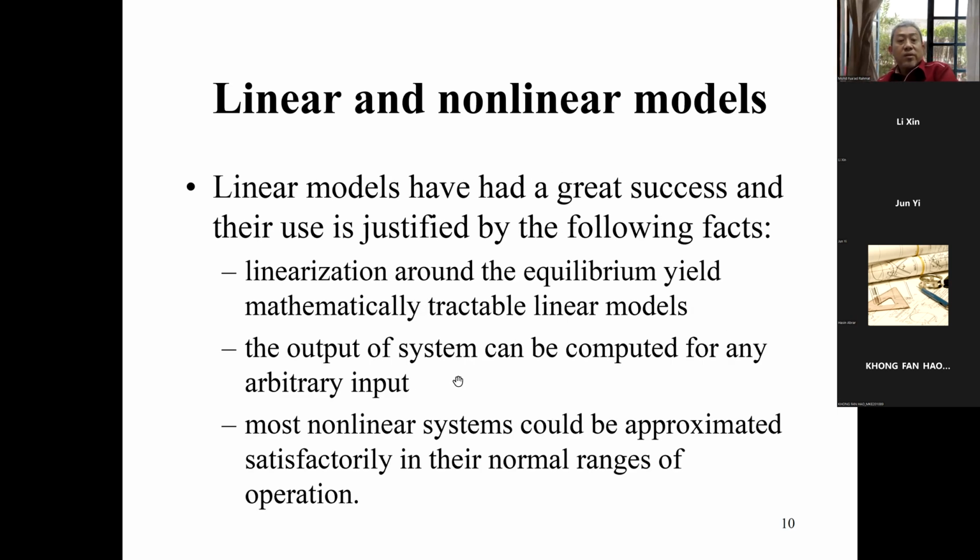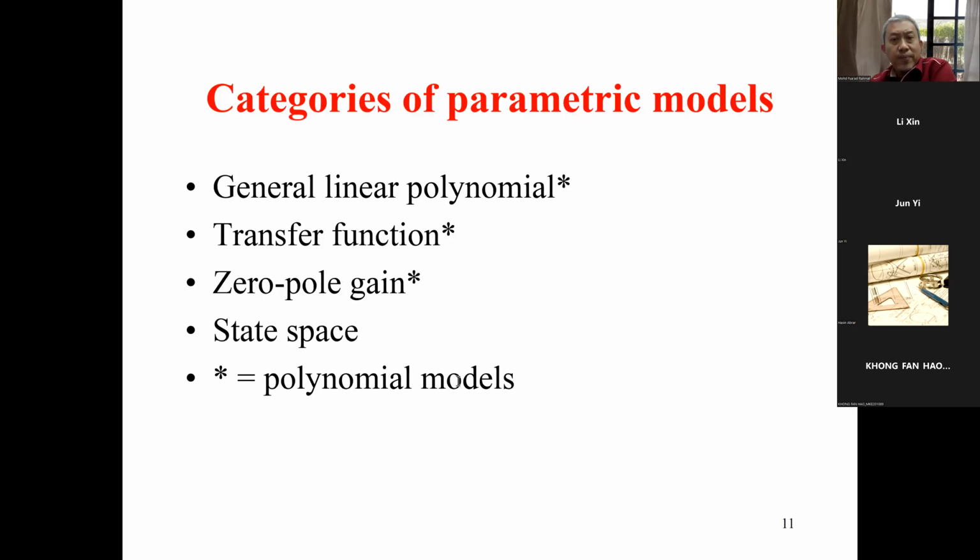Therefore, we use linear models, which can give great success and can be justified by the following facts. Because we apply linearization to the mathematical model, the output of the system can be computed for any arbitrary input, and most nonlinear systems can be approximated satisfactorily in their normal range of operation.